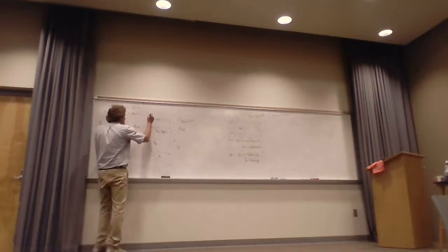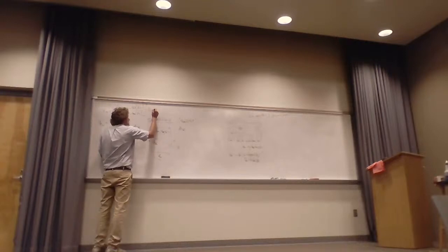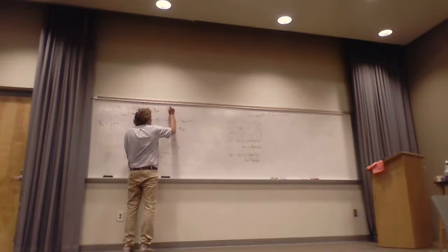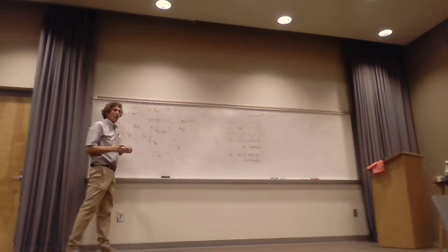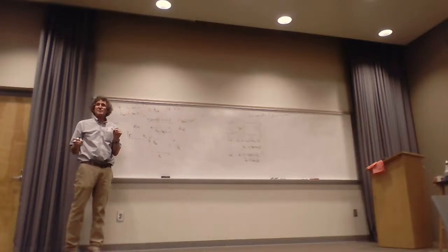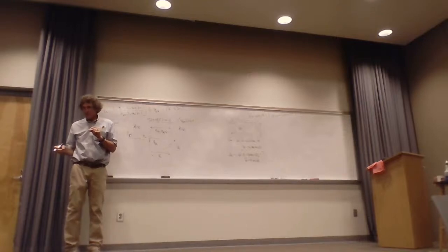We can say this is about equal to just eta of the shield if the skin depth is greater than the actual thickness of the shield. Almost all shields are several skin depths thick. Y'all follow me? And skin depth is a function of the frequency, the lowest frequency they're going to be used at. Everybody with me on that?